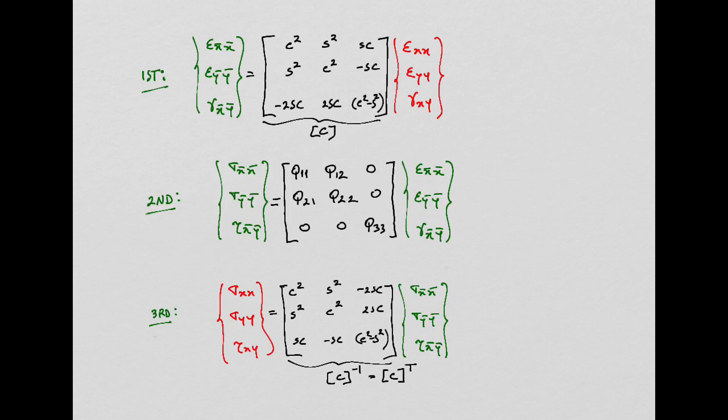The iso in isotropic means equal, equal in all directions. The material properties are the same in an isotropic material, but it's not the case for a lamina, for a ply. So we always have to do this transformation first to get the stress or strain in the lamina coordinate system.